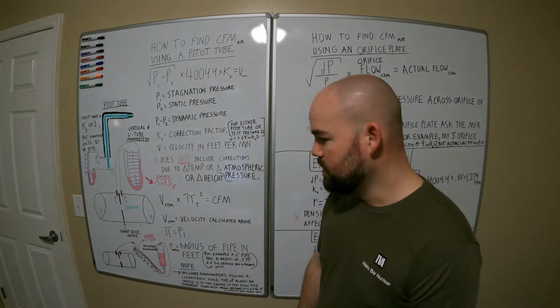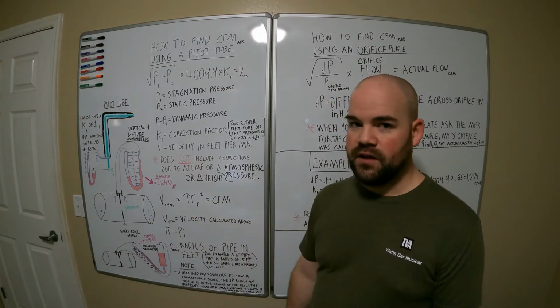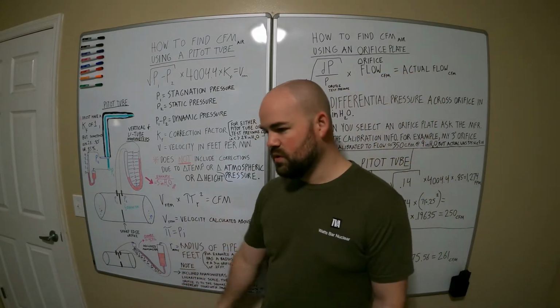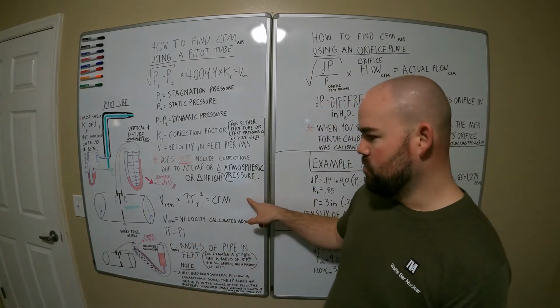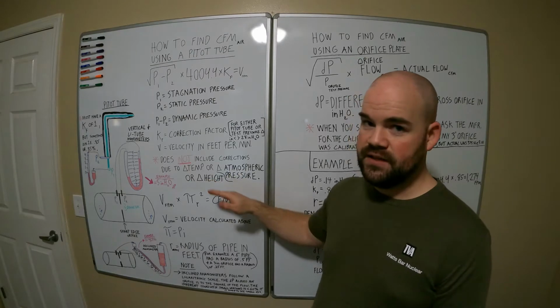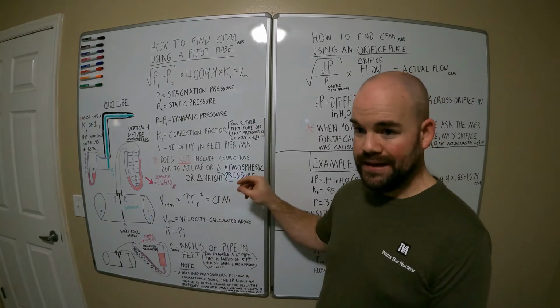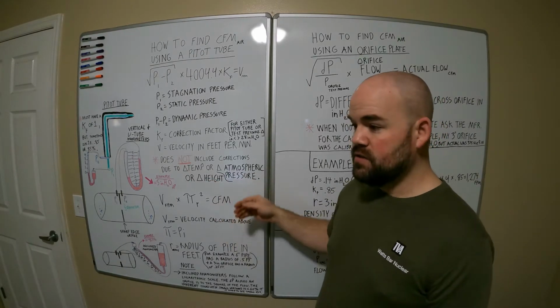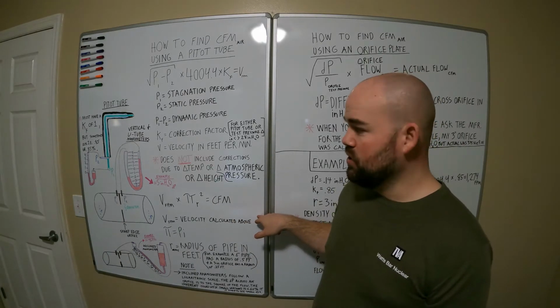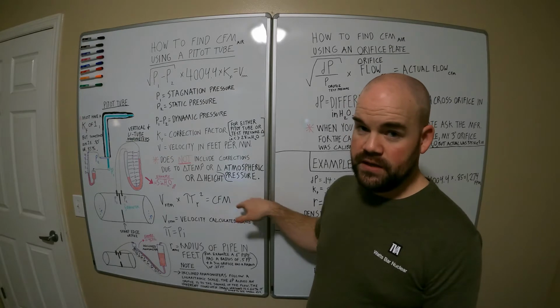And that's because it follows that non-linear rule. Okay, so you can do this, but just remember, for every inch of water that you want to see, you got to make sure that your incline is only rising an inch, right? So if you want to be able to measure 10 inches of water differential pressure, you only want your vertical scale to raise 10 inches.